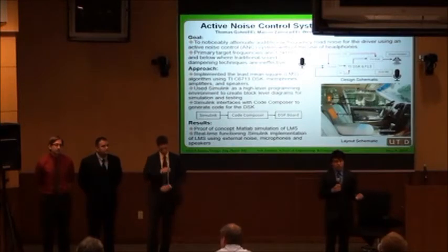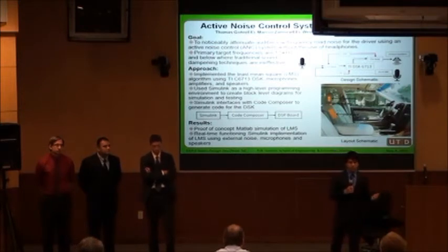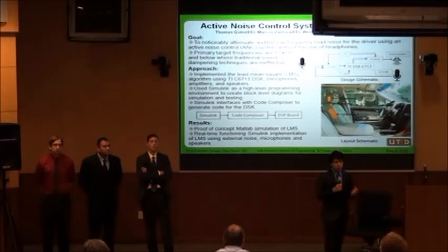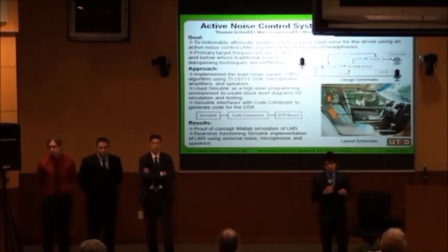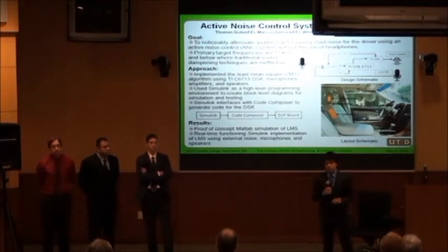What separates us from what's currently in the market is that we're using an active noise control system instead of passive barriers in order to cancel out the noise. In order to do this, we implemented an LMS algorithm on a TI C6713 DSK. This LMS algorithm is an adaptive algorithm which handles the road noise and outputs the anti-noise, which corresponds to the road noise, to cancel it out.